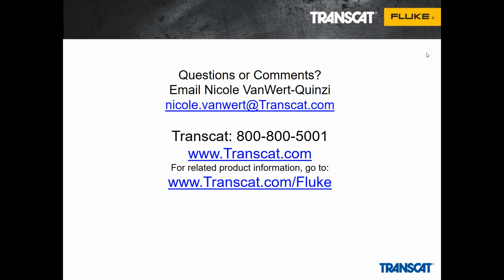That's something the supervisor may have a discussion with the technician about. And one other thing the 729 does that's pretty cool is when you load your tasks up and connect to your HART device, it verifies that the serial number matches the serial number of the device that you've downloaded. So you've verified two ways, not only the tag ID but the serial number, so it matches up exactly.